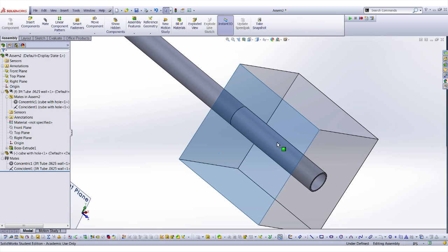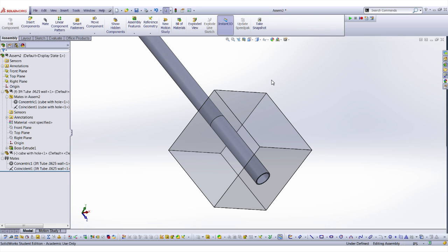So if my mouse is here, normally if I just click it's going to be on the pipe, but if I hold shift and click and I move a little bit, it'll reselect to the face of the object and won't click through it. So that works with all transparent objects, and that'll get really, really useful when you start getting bigger assemblies and you have all of your electronics hidden, or you have a side rail of the robot transparent and you're trying to click through it sometimes.